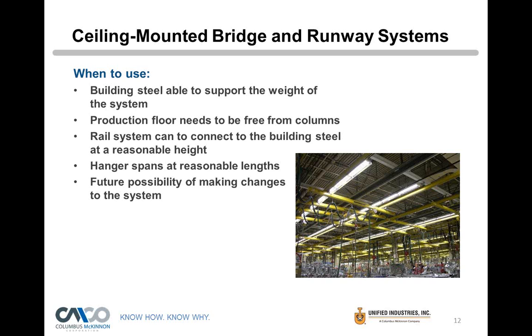If the building steel is able to support the weight of the system, that's when you could use one of these systems. Being from the more northern part of the states, we typically see buildings designed with heavier steel structures to support the weight of snow. We've seen sometimes down south, a lot of the buildings maybe don't account for what's called a snow load. So you'd want to check with the facility in question. They usually have drawings, or the facilities engineer would provide you with something to prove out that an overhung system would be safe.